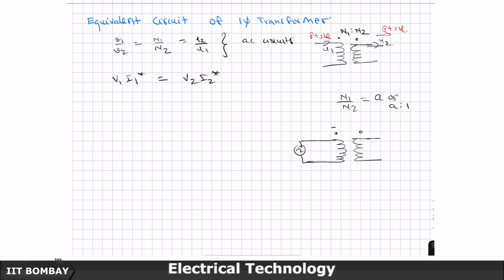An ideal transformer has I1 equal to 0 and I2 also equal to 0, but because of the finite mu r, even if large, which is associated with the transformer winding, I will have some magnetizing current flowing through the source into the transformer, but I do not want it to flow into the ideal transformer.